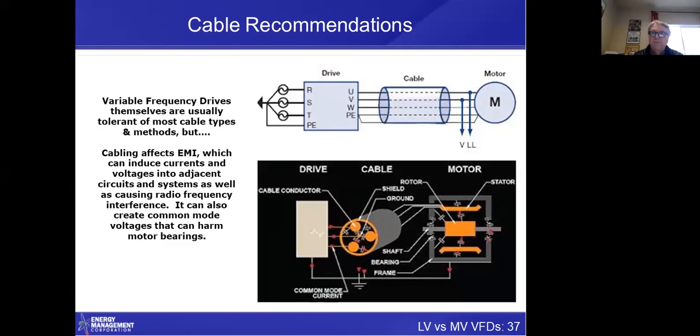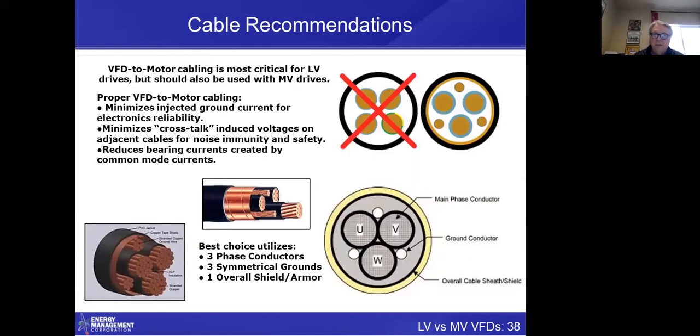Now that special VFD cable looks like this in its best version. So you have your 3 conductors all symmetrical in a cable. Then we have 3 grounds, not 1 ground, but those 3 grounds keep the ground voltages symmetrical. And then around the outside, you have an overall shield of armor.